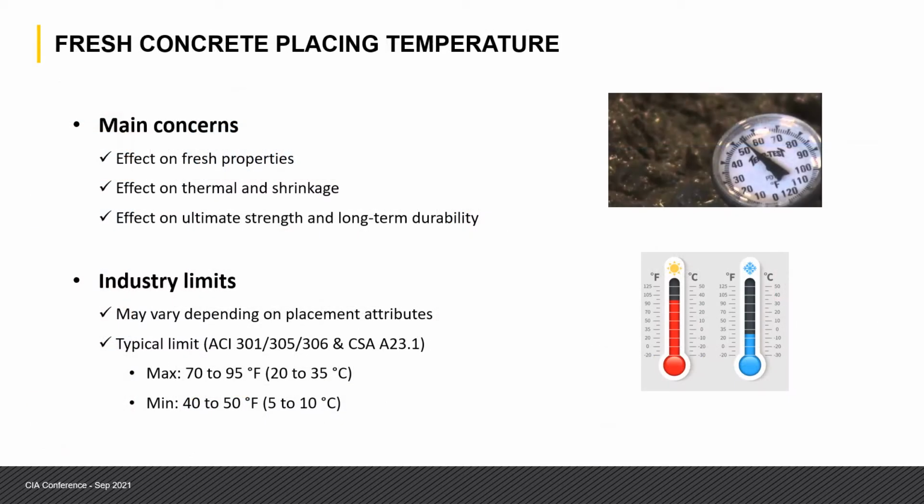Now, when we talk about fresh concrete placing temperature, it is important to understand what the effects of that are. Higher temperatures can impact the fresh concrete properties, the thermal behavior, shrinkage, and even affect long-term durability and ultimate strength. So what are the limits that the industry provides in the North American market? And this is going to vary by placement attributes.